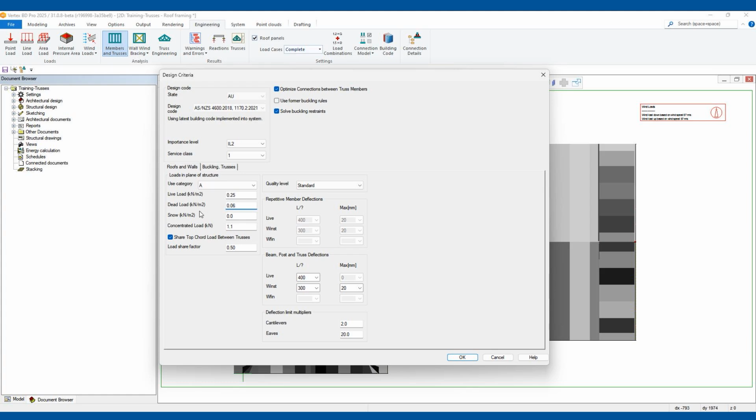a sheet roof. The other thing, this makes a big difference too, this load share factor. I think the code says it can be set to 0.5. What that does is halves this value. And because this is a live load, this concentrated live load, that's already multiplied by the code by 1.5, so that's going to be like 1.6 roughly, which is quite a lot, 160 odd kilograms. So the code says we can halve this. So this is essentially people walking around on the roof, and yeah.